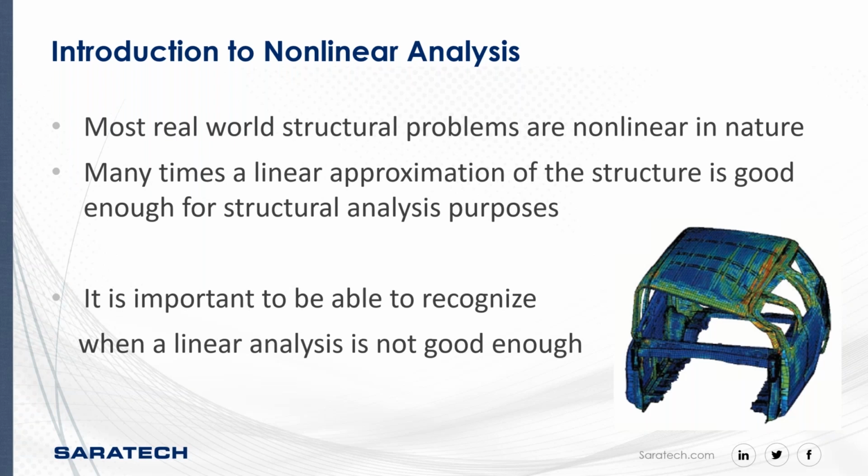Most structures are actually nonlinear in reality when you're loading them, because the stiffness of the structure is changing as you're loading it. But most of the time, we just use a linear approximation, and we assume that's good. But it's important to understand when that's not good enough.